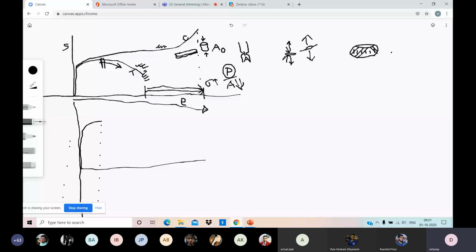But if it becomes too thin, then there are shear cracks along the shear stress. Too much deformation along certain shear bands leads to separation of metal. But that will happen at a very high amount of deformation, more than 90-95%.